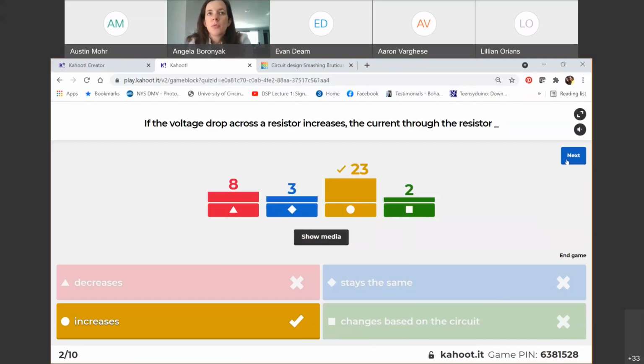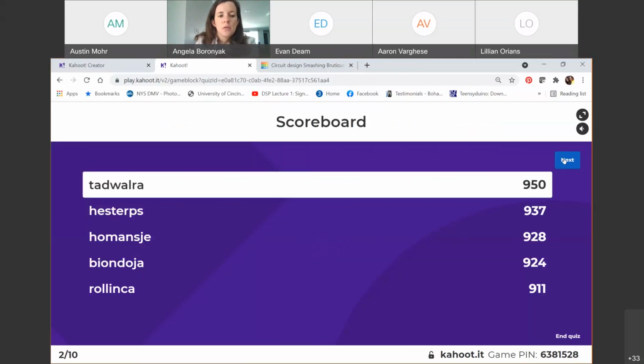Make sure you are comfortable with Ohm's law forward and backward. I know you don't have to memorize it, but it is helpful. Make sure you know that it is the voltage drop, which direction the current goes across the resistor, and how it plays a role with power, plugging into our power equations. Those are all things that can ask relationships like this between resistance, current, voltage, power, all that good stuff.